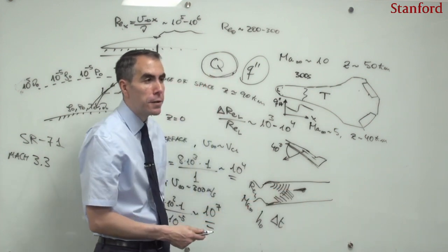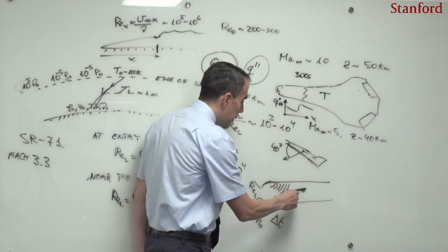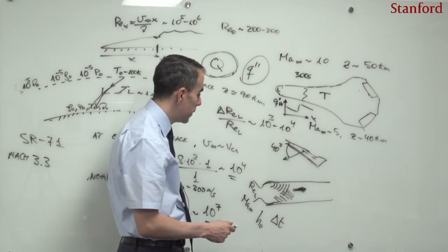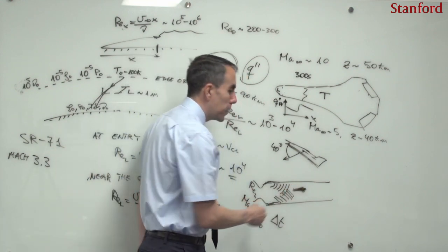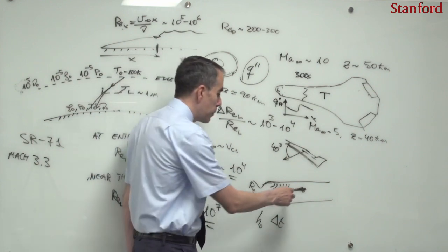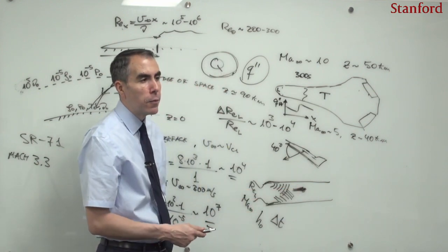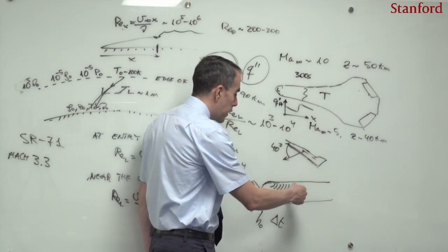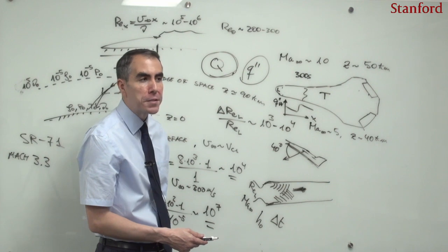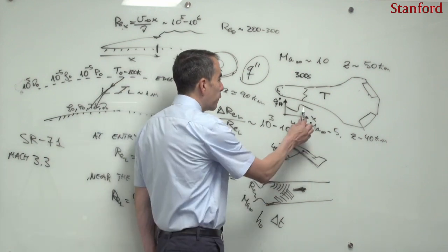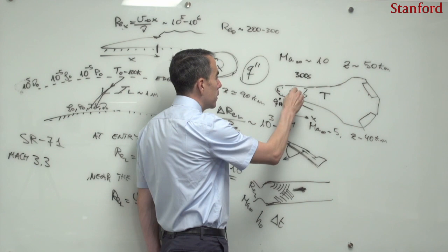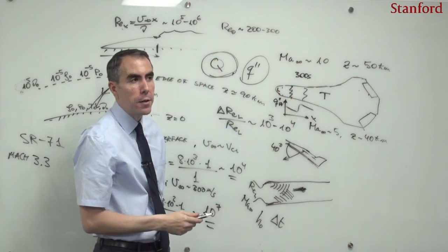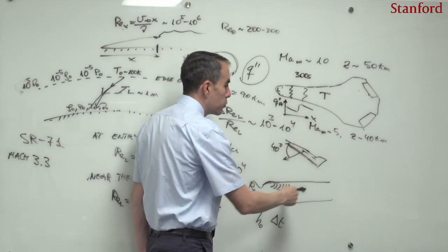And those acoustic waves interact with the boundary layer, overriding the test model. And as a result, that noise actually has an important effect on the outcome of the prediction. One of the discoveries in that paper by Goodrich is that the wind tunnel measurements were always overestimating transition. So if in flight the front was there, the wind tunnel measurements will always give you an advanced front, and that is because the wind tunnel noise was triggering transition.